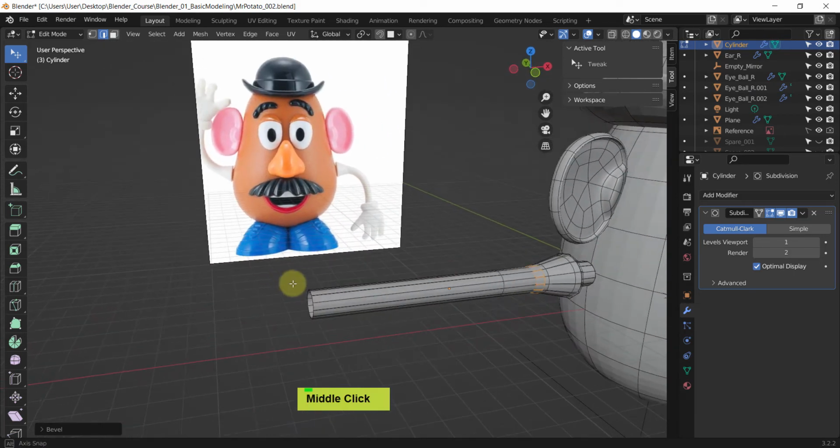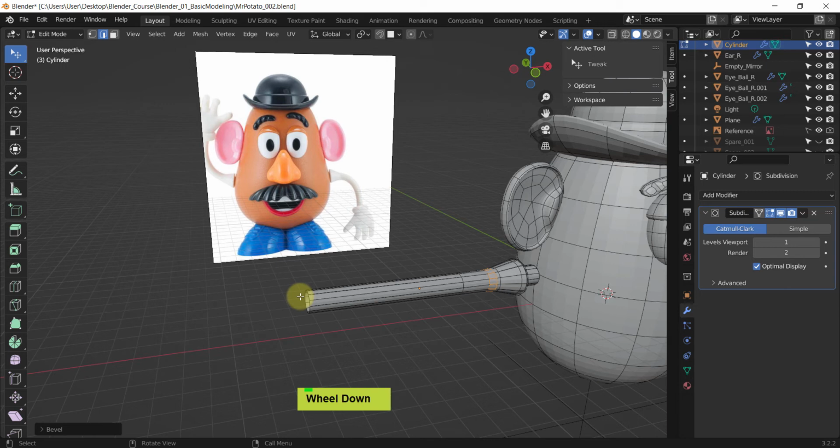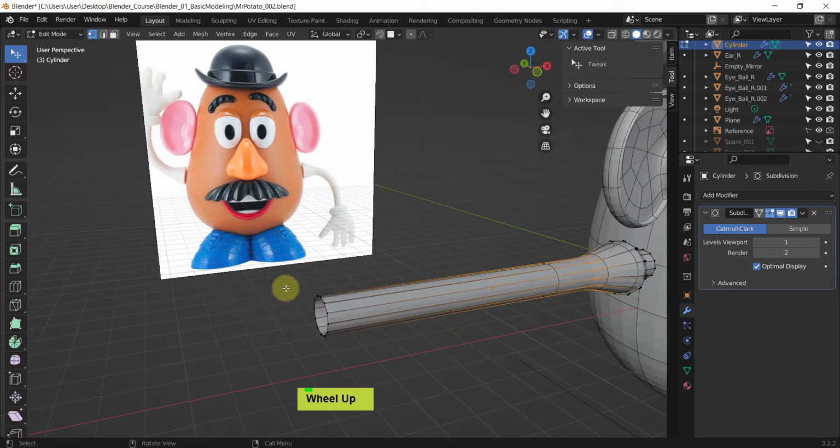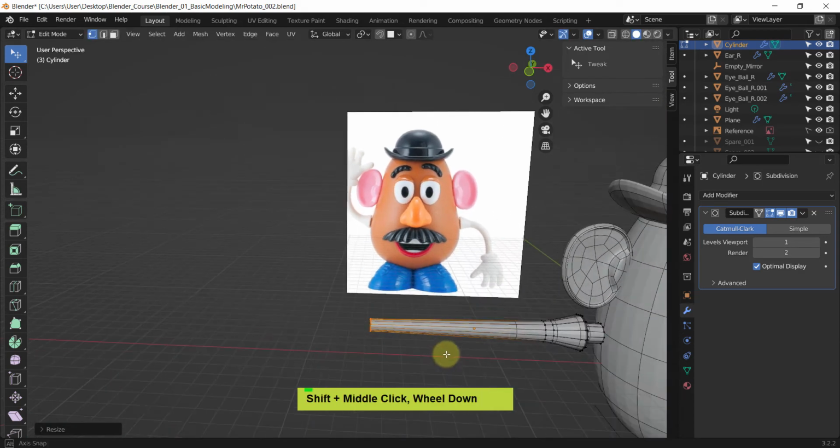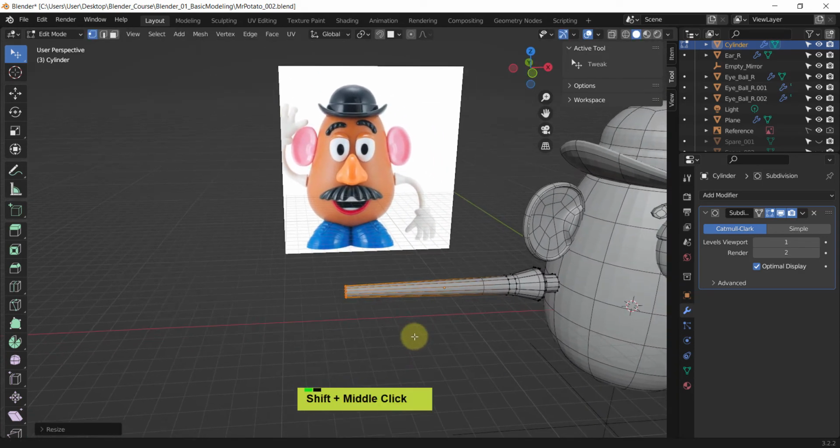I will shrink this area, so let me go to vertex mode, and make sure that every vertex is visible here. So I'll select with the B all of these vertices and scale them down a bit. Oops, I have an existing selection, so B, and scaling down a bit to make it a little bit more pointy. Alright, which one is a little bit more believable here?